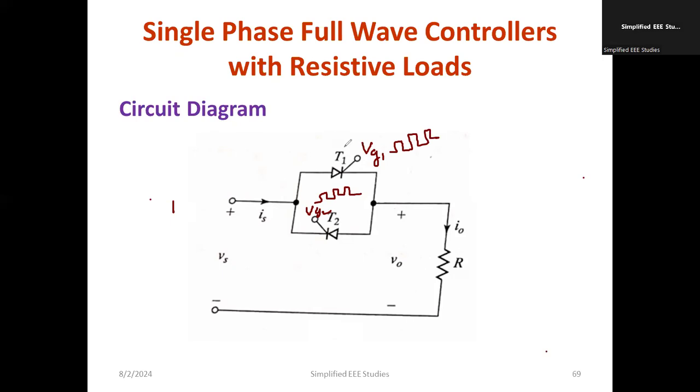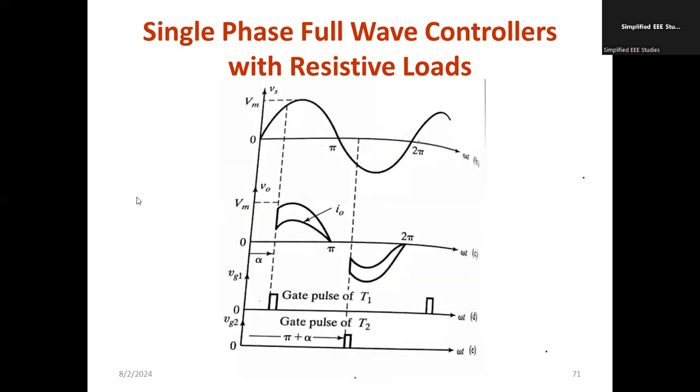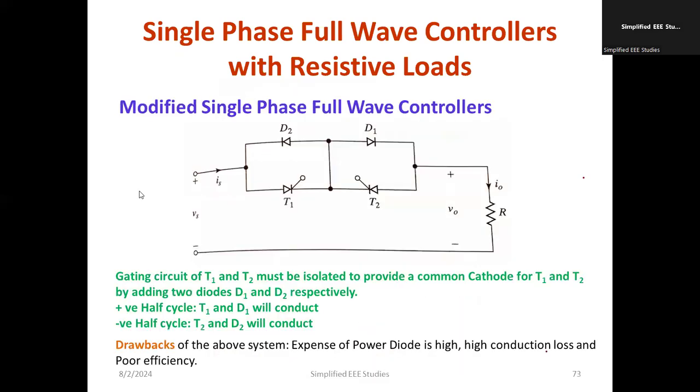But the thyristor can operate at more than 100 kilovolt. So the problem is there is no isolation between the signal level voltage and the power level voltage. There is no isolation. So what to do? If we are not providing an isolation, our gate circuit is getting spoiled because of the heavy voltage. To overcome that, you will be doing one new design called the common gate technique.